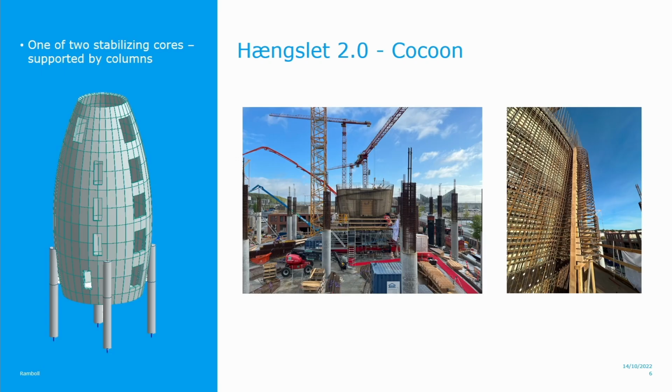Yeah. The cocoon, this is approximately where it is now. There's some casework on the outside now also, but all this reinforcement had to be hot rolled into the shape because it is 16 diameter, so it's not something you can just bend on site. And they have spent a lot of time on this because, again, the visibility of the surface is extremely important for the finished project.